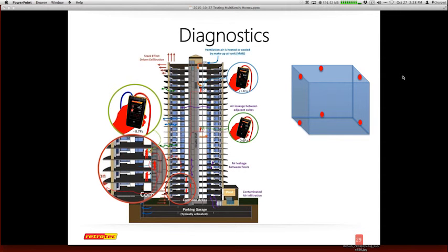And if there is a parking garage down below, this is one of the things you're really trying to find out if you have a connection to. So even before you're able to test, a lot of times you can determine if the parking garage, compared to just a few flights above, has a positive or negative connection. So again, all these things can be done by just doing some detailed diagnostics with a single gauge throughout the structure.